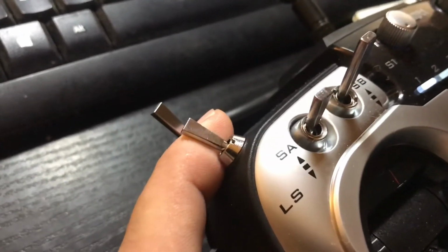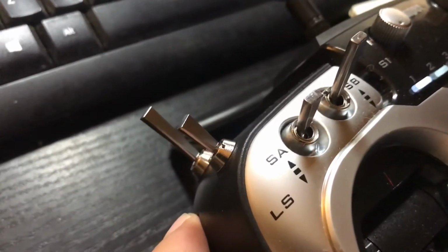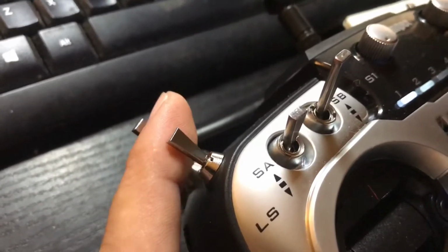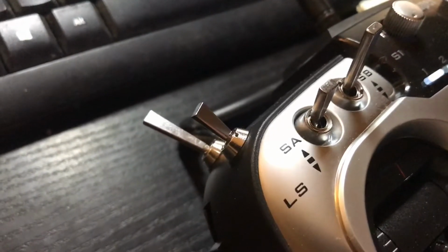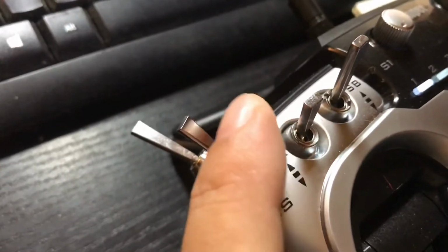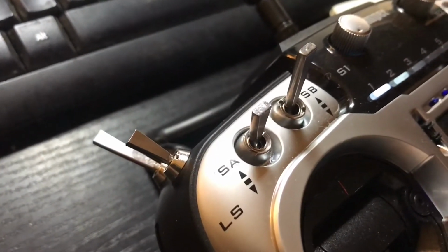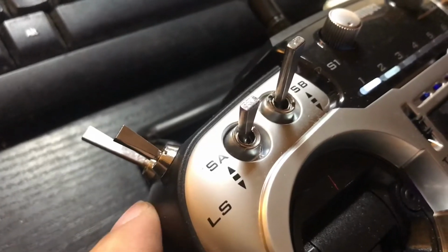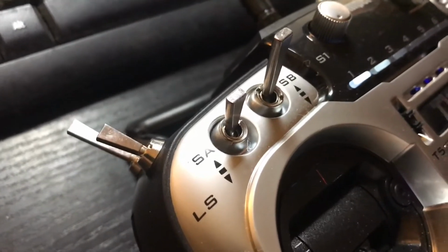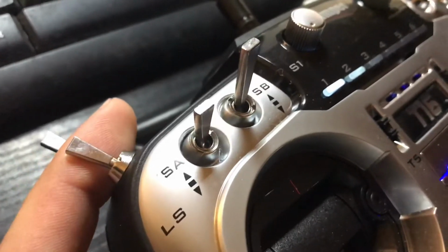So I'm preparing to land. I turn on the landing lights. I've landed. I turn off the landing and turn on the taxi lights. Right? I'm in the parking lot, so I switch, and I only have nav, strobes and beacon. I've disarmed the motor, only nav and strobes. If I am about to turn off and disconnect the battery, I put it there and I have the system all off. So as you see, this is a natural sequence.